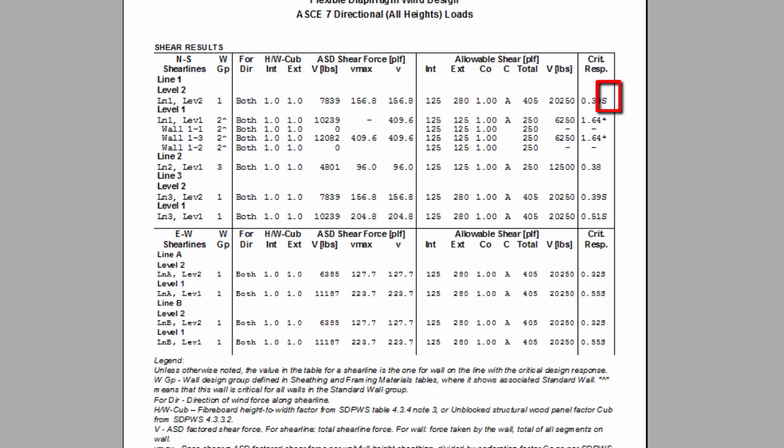This feature is called the worst case rigid versus flexible diaphragm design, also referred to as envelope design. Essentially, Shearwalls version 10 now compares the walls designed for wind and seismic and selects the wall that has the highest capacity to redistribute forces on the line if deflection is the force criteria. Consequently, the selected wall is also used to redistribute forces to the shear lines for the rigid diaphragm procedure.